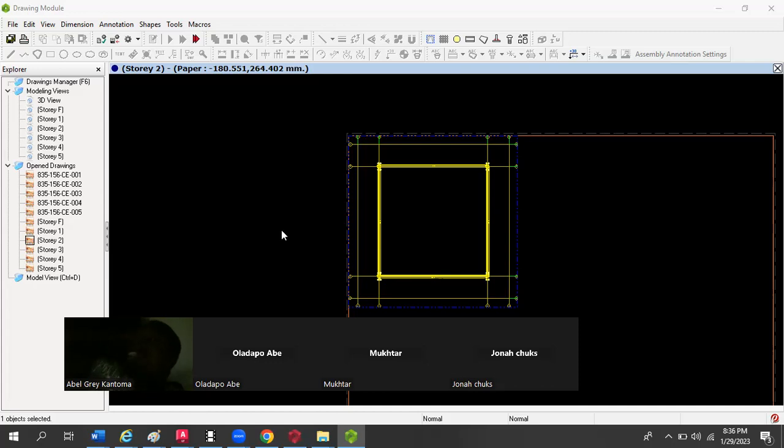Don't forget, it even has a foundation down below, which you may probably want to choose, whether you are using a strip, an isolated pad, or it could even be a pile, whatever kind of foundation, you have to generate that too. That's for the reinforced concrete. Then when it comes to the steel members, that's the stanchion, the base plate, and whatever they are using, whether it's a nut, that nut that is there. Even that base plate, that stanchion on top of that base plate, sometimes you even have a weld in order for you not to be having a clash.